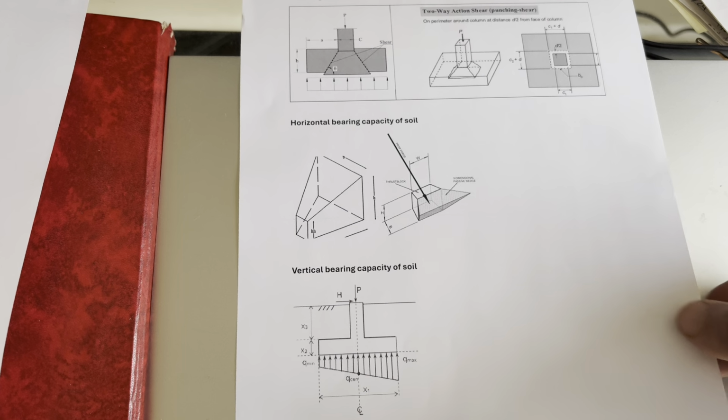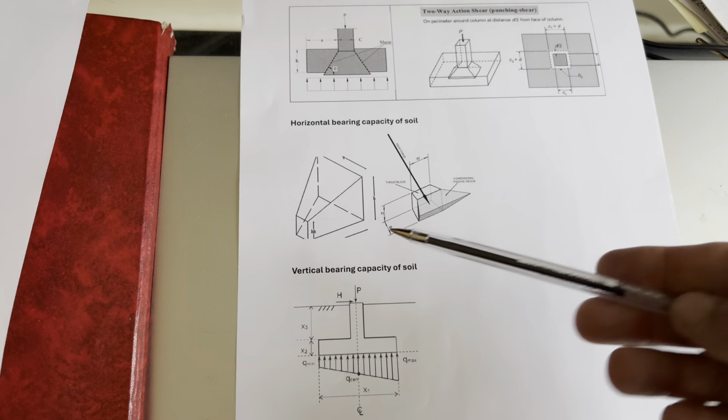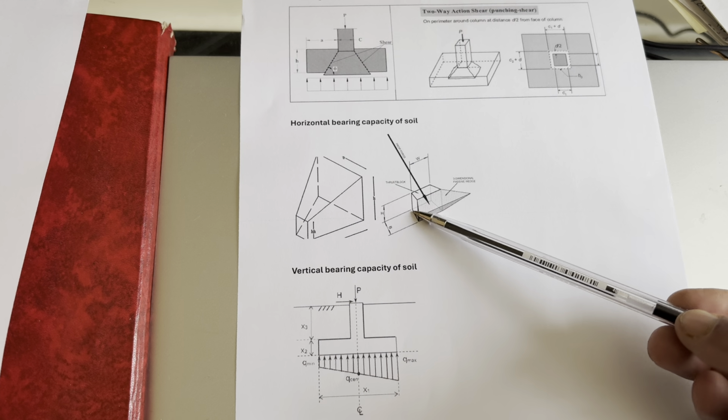Okay, those are very simple and basic principles for thrust block design. Just remember, it is very basic, but always make sure to check step-by-step rules for thrust block, anchor block design. You rely on the bearing capacity of the soil, horizontal and vertical, and if we have uplifting, in general, we rely on encasement. The gravity of the encasement should take the piping system down. And in the encasement system, in most cases we have reinforcement, but in cases like this, we may need reinforcement or we may not.